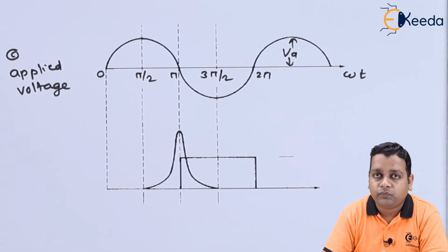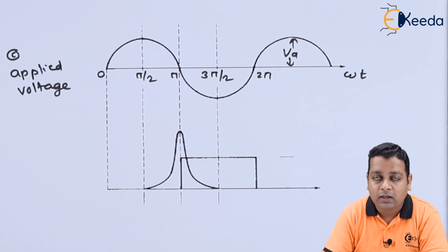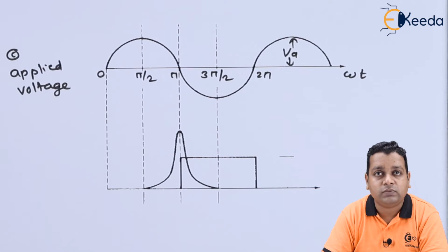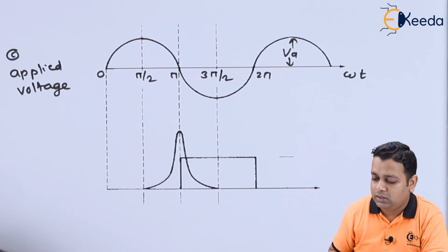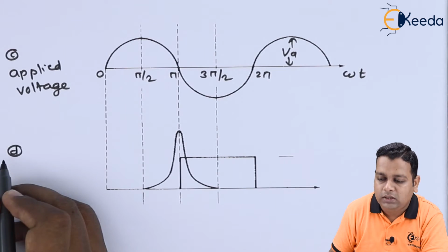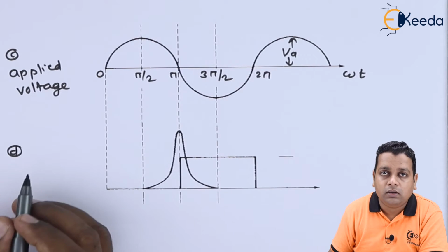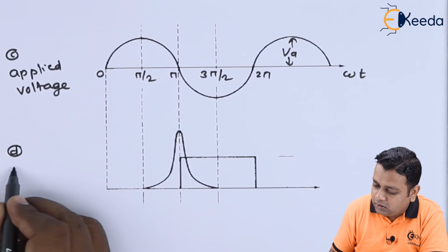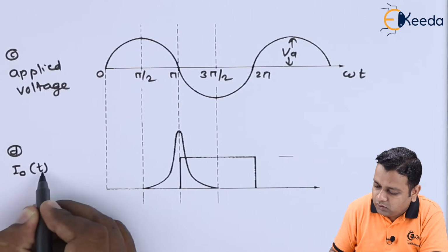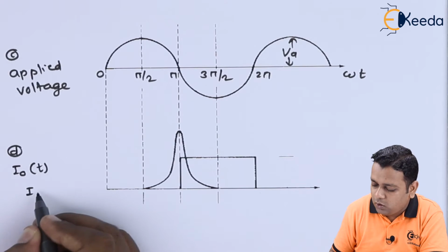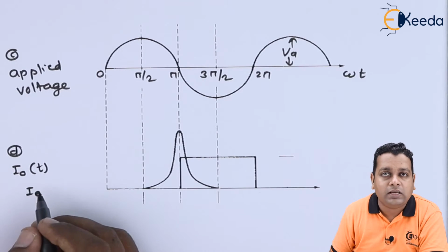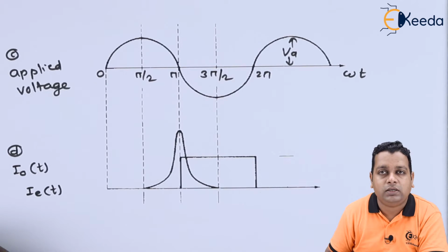Now we know that the applied voltage is at the N plus, which is at the left extreme, and after the avalanche effect that takes place in the second region of P type, we obtain the current pulse represented in figure D. In figure D, we can represent the current values, or simply the current form, by I suffix 0 as a function of time t, or for the output we can take the extraction I suffix e as a function of t here.